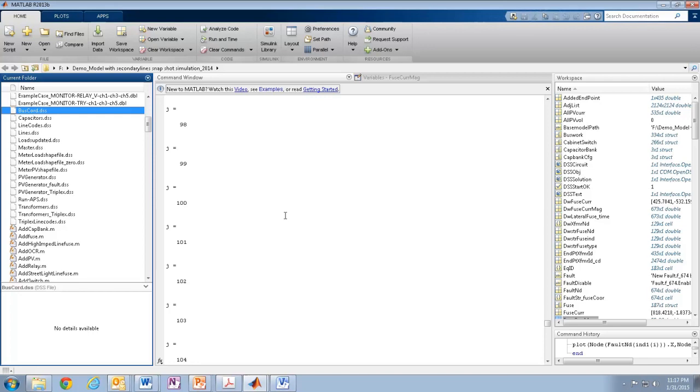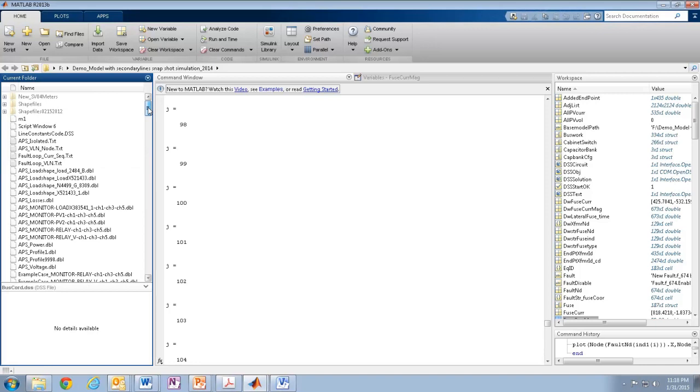Okay, so next I wanted to show some of the outcomes of this from MATLAB following the various modeling processes that I described. I'm going to look at some of the text files that MATLAB created in a format suitable for OpenDSS to do various OpenDSS workflow analysis. So this is all part of the protection analysis toolkit that you should have.